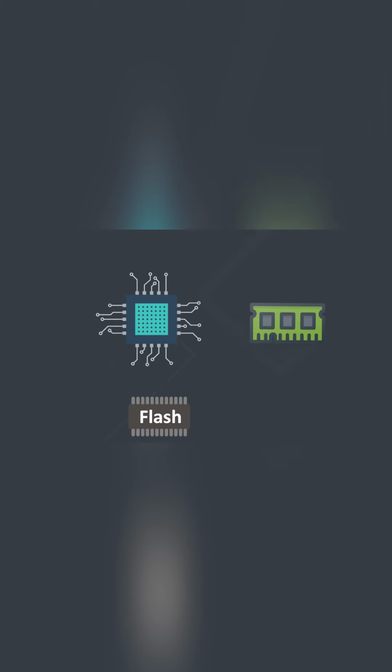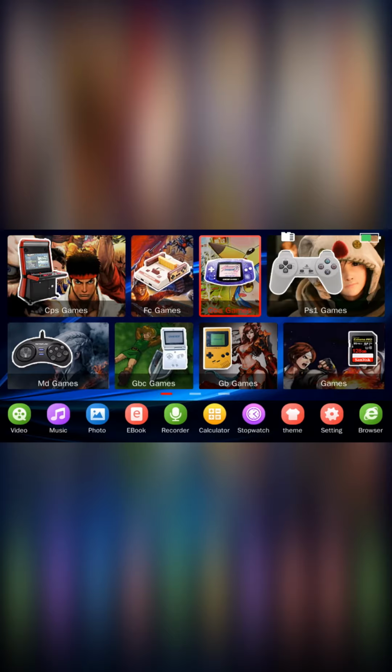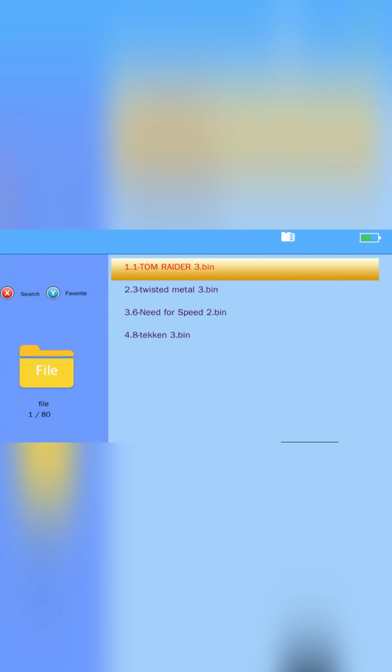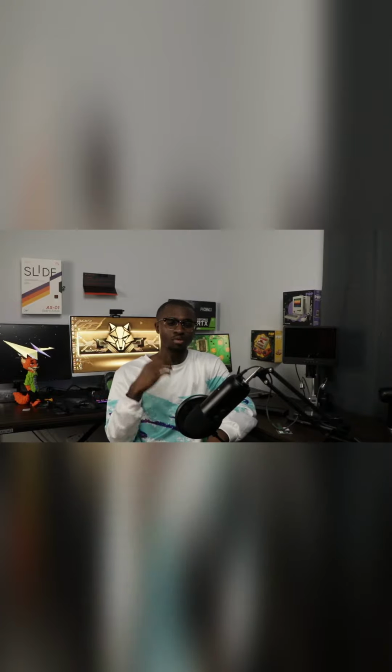So for some reason, they decided to put the latency sensitive RAM package further away from the CPU that desperately needs fast access to memory. You can clearly tell this device suffers because the operating system is extremely slow. The system is already being neutered because of the insufficient RAM, in my opinion, and you go and make that worse by having the very slow eMMC NAND act as a proxy for your RAM. That makes no sense to me.